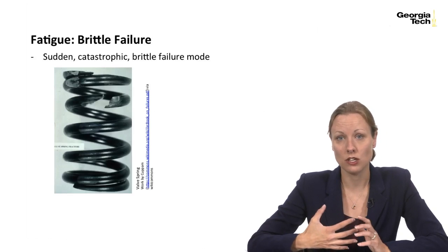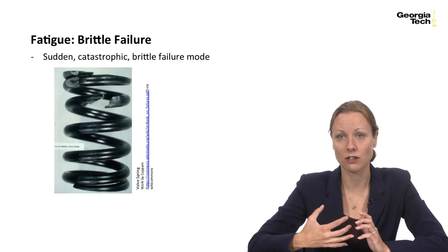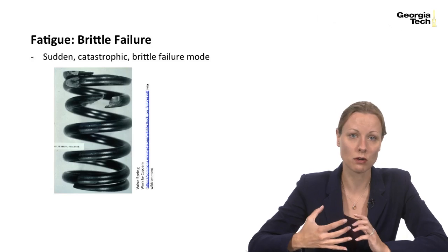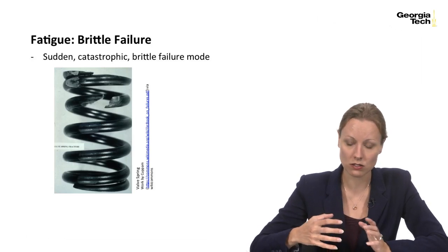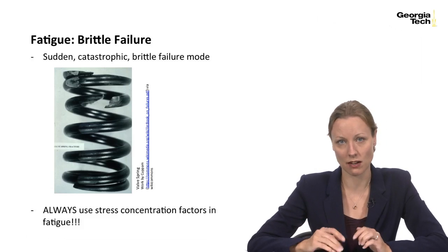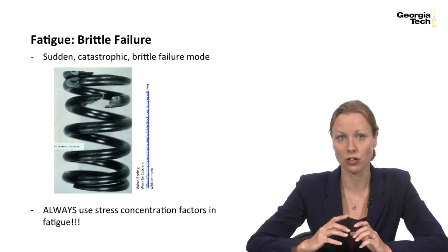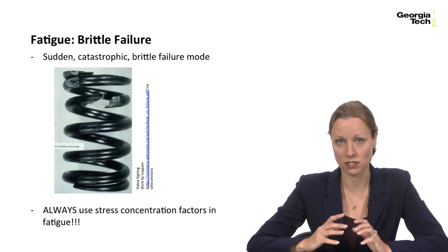So in fatigue, you have these sudden catastrophic failures that are somewhat brittle in manner. So even if your material is ductile or brittle, you always have to use a stress concentration factor when you're operating in a fatigue condition.